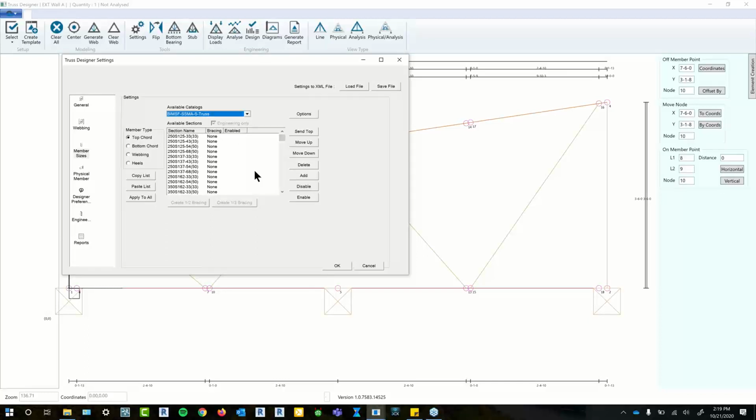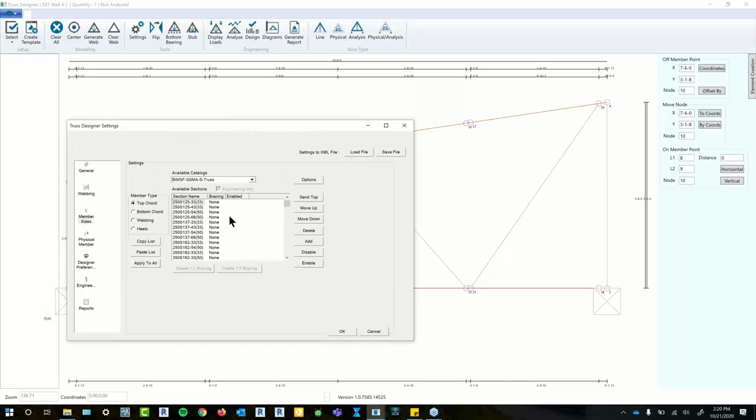All right. So in terms of the analysis, it works exactly the same way as advanced metal, and it just works by pick list. So how our designer works is that according to this list, it's going to look at your webbing, your loading that you've inputted, and then according to all this information, it's going to tell you if the size passes or fails. So if I do hit design, I can basically just have it run through this list and try and find an appropriate size.